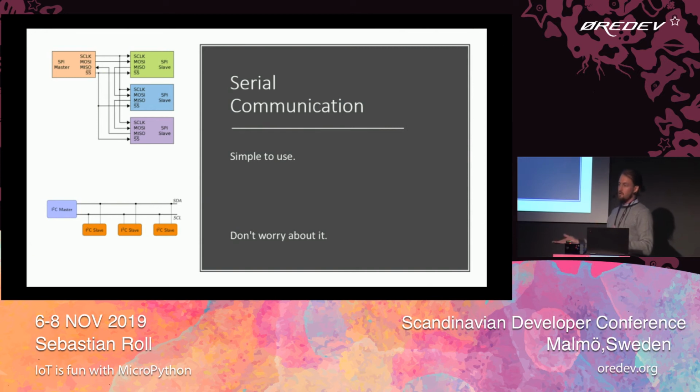For serial communication, you bought a sensor at AliExpress and you want to connect to it. So mostly what you're going to be using are one of 2 protocols. The first one is SPI, and the second one is I2C. So you can see the I2C, the bottom one, has a clock pin, that's the SCL, one clock pin that just goes up and down at a speed, and then a data pin, which sends the data synchronized. So you can see that for the I2C, you can have multiple components on the same 2 pins, 2 wires.